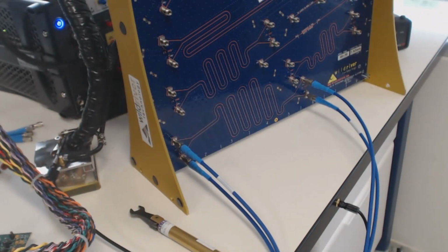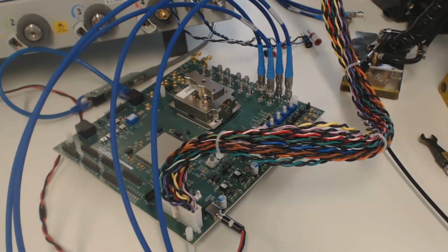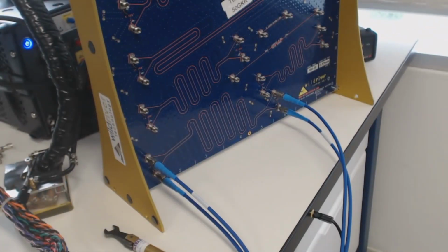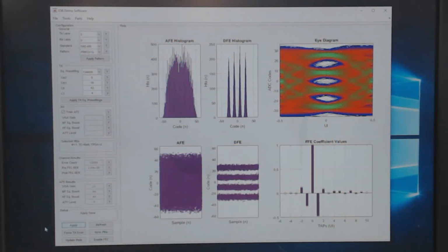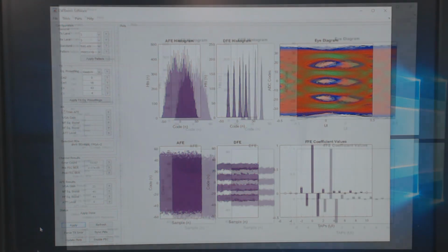The 56G Ethernet test board and its transmitter and receiver ports are connected to a 31-inch channel on the Wild River ISI board. The total loss, bump to bump, is 40.5 dB. Once again, we configure the transmitter data rate, pattern, and equalization. Again, we can see the diagnostic plots of the recovered signal at the analog front-end output and the DSP outputs. The two-dimensional non-destructive eye diagram shows open eyes. However, as expected for these higher loss channels, bit errors will occur with PAM4 due to the lower signal-to-noise ratios and higher sensitivity to non-idealities like jitter and ISI.